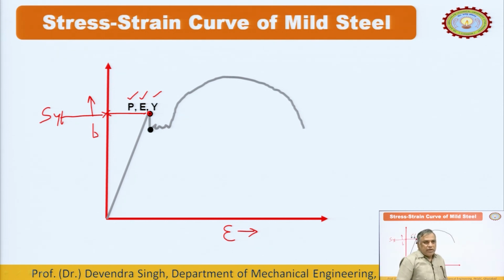This is the strength at yield point, and as soon as you reach yield point, the flowability will take place and there is a drop here. This is a drop in the resistance or the stress. So, this point is called the lower yield point Y L, and after that this zigzag zone of the curve is nothing else but the rearrangement of the molecules or atoms, and this is called strain hardening. And beyond strain hardening, the mild steel will regain its resistance, power or strength.